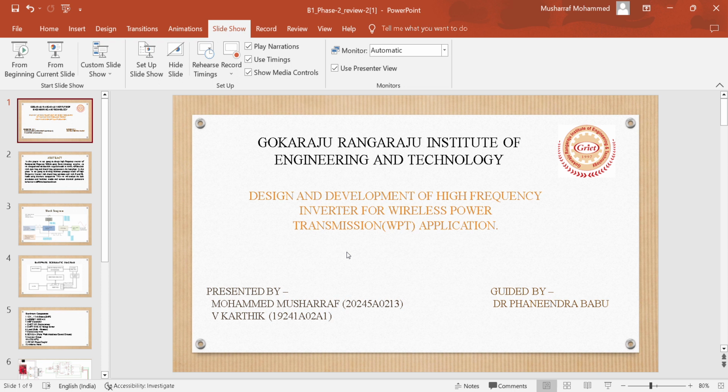Wireless power transfer depends upon transferring energy inductively from one coil to another coil, which requires a high level of inductance. For that we need high frequency. There are many advantages of using high frequency. Among them, the size of the components will decrease and the value of the inductance will be increased. With a smaller number of components you can produce more inductance.